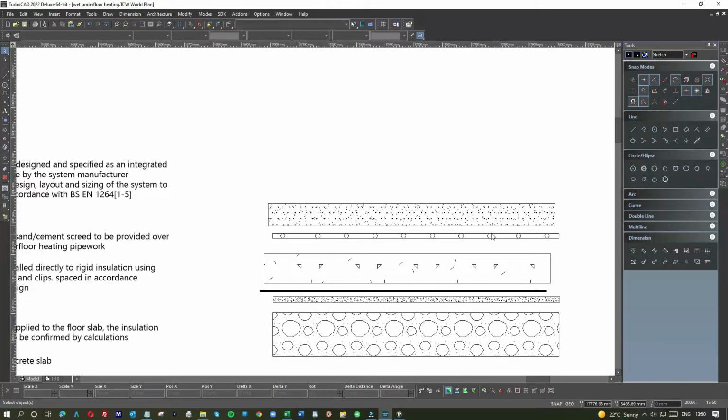They're usually 16 mil, but they can be much tighter than that depending on the installation and what they're trying to achieve. Underneath that we have a thick concrete screed. Underneath that is DPC, and then it's usually some soft sand, and here we have the rubble that's blinded with a bit of ballast, and then the soft sand on top.